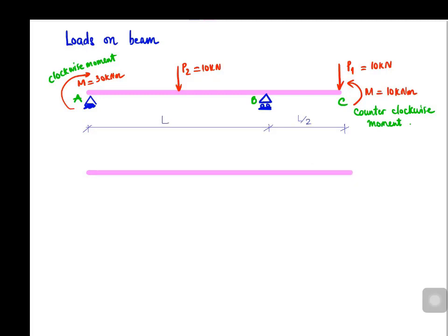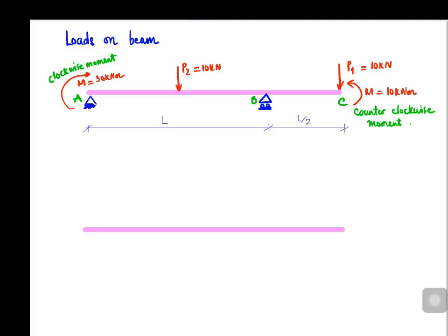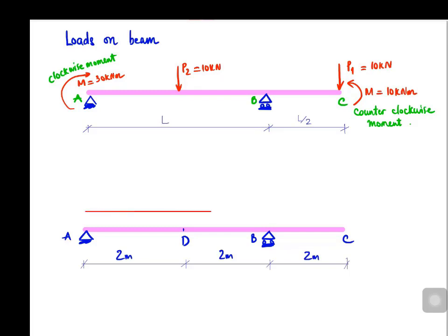Turn to distributed loads. When the load is spread along the axis of the beam, it is represented as a distributed load. Distributed loads are measured by their intensity, which is expressed in units of force per unit of distance. A uniformly distributed load, or uniform load, has constant intensity q per unit distance. It is represented as so, with its constant intensity of 10 kilonewton per meter.